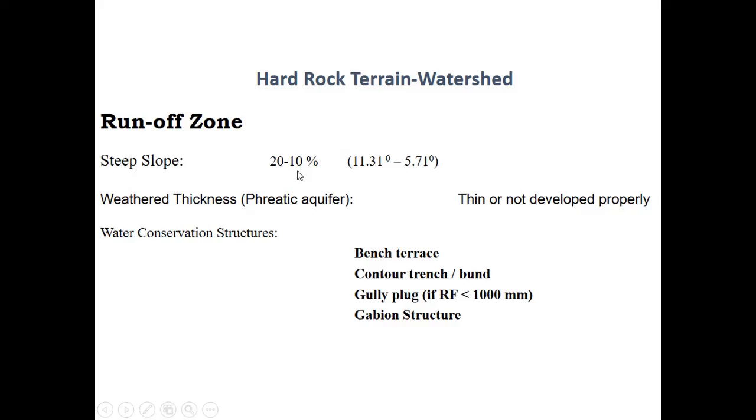10 to 20 degrees, and these are highly weathered. They are very thin or not developed properly. The water conservation structures to be taken in this hard rock terrain where the runoff zone is there are bench terrace, contour trench or bund, gully plugs and gabion structures.